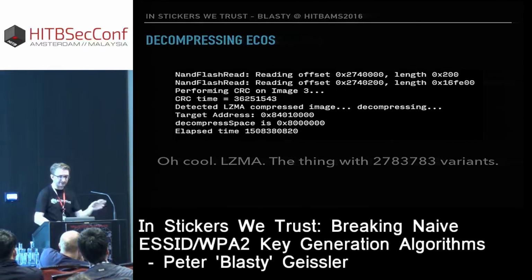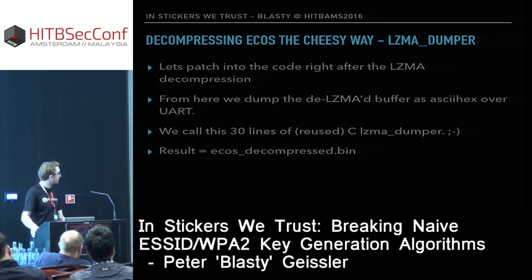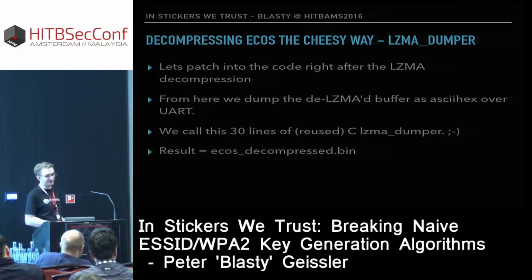Seems like everyone likes to change something in the LZMA packer or unpacker. I'm not sure if that's obfuscation or just being annoying in general, but I came up with a different way, right? I had this way to do code execution really early on, so I could patch things. So what if we insert a code patch right after it is done decompressing that buffer to memory? And then we just dump the decompressed buffer over the serial port to our computer.